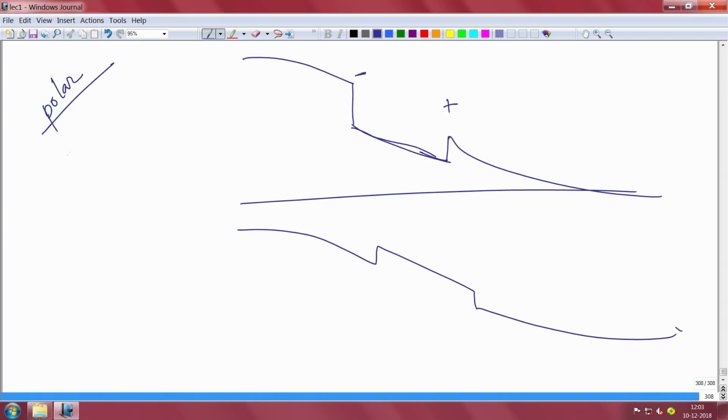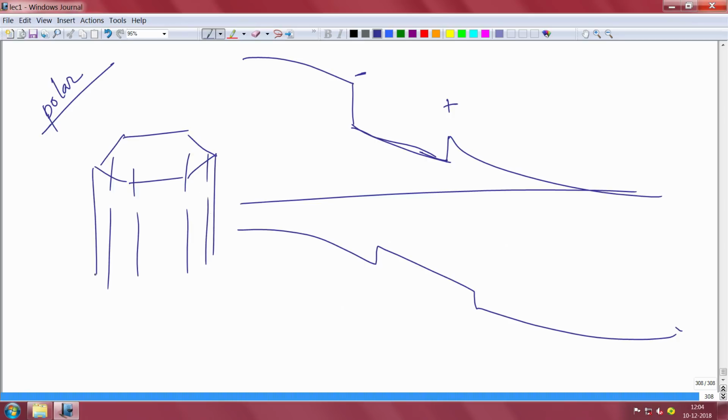But nowadays they are going to, if you have a gallium nitride crystal like this, right? I'm not drawing it very well, it's just a unit cell. If you have a gallium nitride crystal like this, then this is a C direction, this is the growth direction, which is called C, and this is a wurtzite structure. So the direction convention is 0 0 0 1. Okay, that is this direction, and this is the polar direction, and so you have a high field.